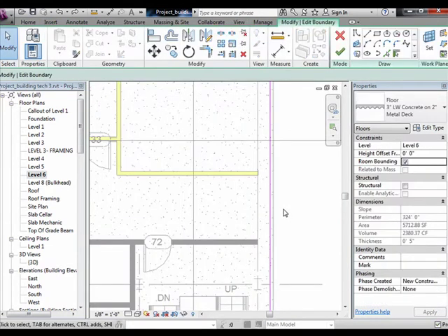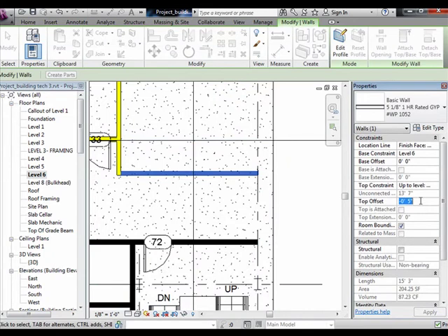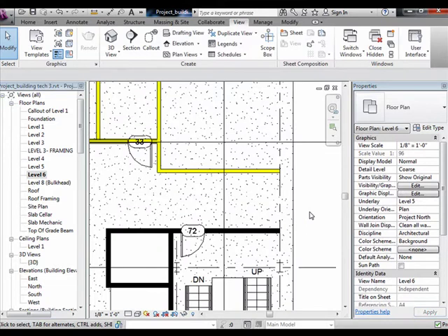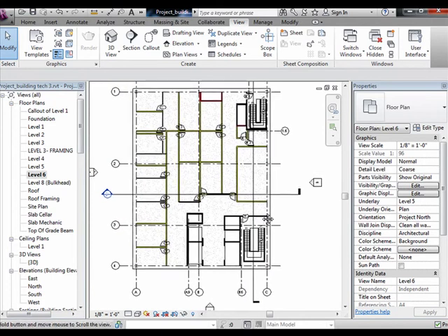Okay, it didn't give me that option, but when you adjust the floor and you have partitions below, you get this pop-up. Do you want to attach walls to the bottom of the slab? If you hit yes, that 5 inches on all the partitions gets put in automatically. Problem with that is it's constrained to the floor above it, and the pluses are if you modify that floor, the walls go with it. Negatives, sometimes you want to modify the wall, you modify the door, you do something to the wall, it'll give you hell of errors because this stuff is constrained to something else above. So I generally use no constraints. Do not attach.